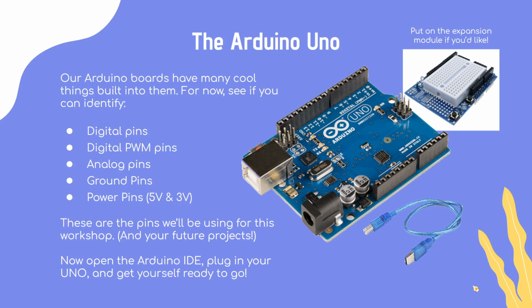We'll get into that when we get to the coding part. When you declare a digital pin in Arduino IDE, you just declare the number of the pin. But when you use an analog pin, you have to have the prefix A, capital A, and that lets the processor know that you're using an analog pin. Otherwise, it's going to think you're referring to something like digital pin 6 instead of analog pin 6. Okay, and then we'll be using these pins for the project.